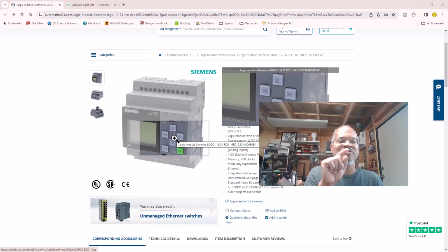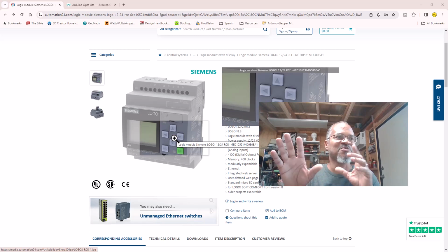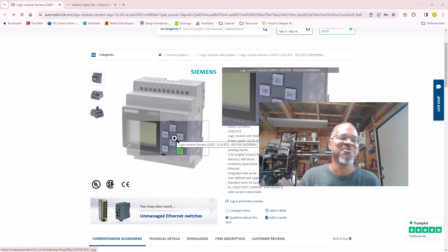When you found the function that you needed, you selected the function, then you selected the conditions for that function, and what that function triggered on the output. So what condition to set the output to. And you had timers and functions like that. So an input came in, a timer ran through a certain amount of time, and then it triggered the output, things like that.